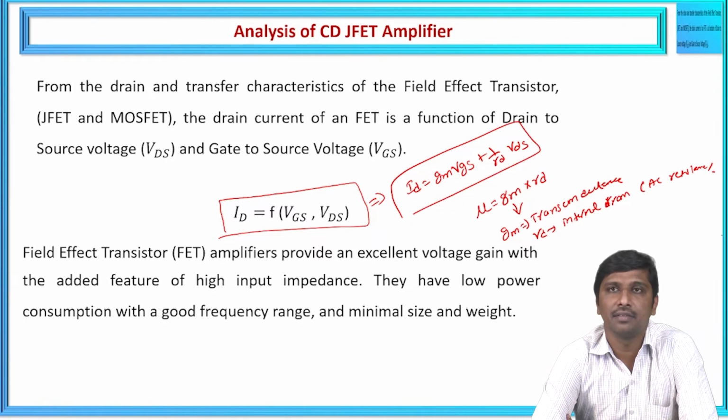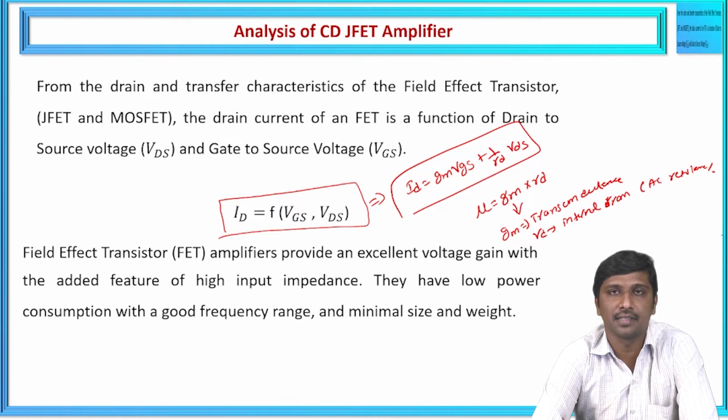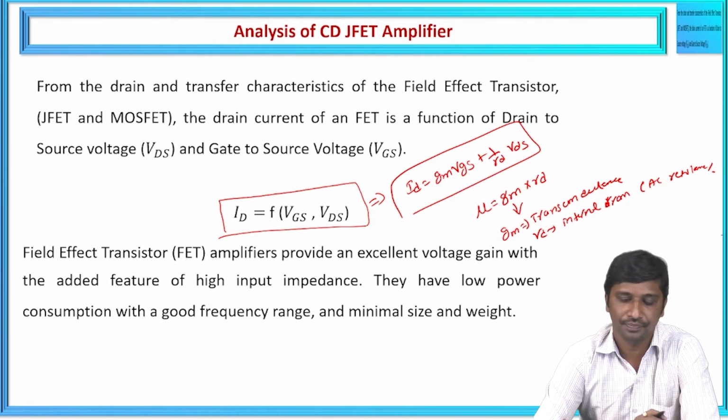Why? If the external load resistance is very small compared with the internal resistance, the current generated should flow through the external load rather than through the internal resistance. To allow the maximum current at the output side, the load resistance should be very small compared with the internal AC resistance. Only then does the maximum current flow through the load device.